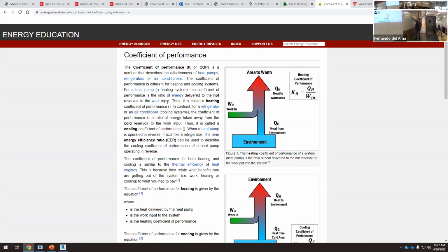I need the maximum power and I need the COP. Those are the 2 concepts that I need from my heat pump. What's the maximum power? It has to be more than this. Okay, it can be 80,000, but it will be much more expensive. If I only need 40,000, something around 40, 45, 50.